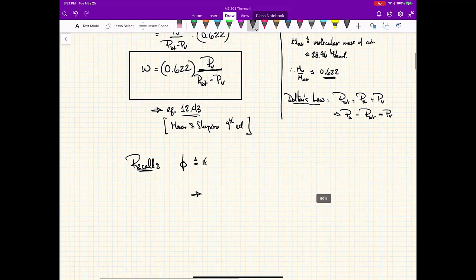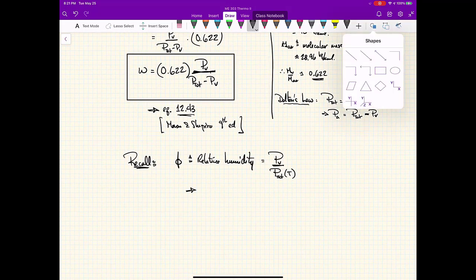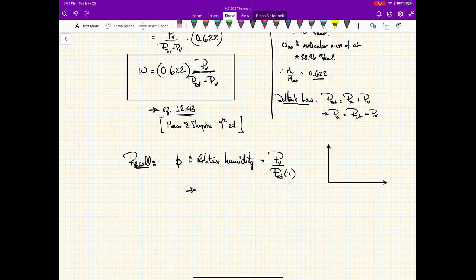relative humidity, and if it helps you, because it certainly helps me to think of it this way, you can look at it on a TS diagram where the saturation curve looks like that. Here's the saturation zone for a mixture at a given temperature, but I'm not there. I am on this isobar instead because I'm superheated, right?